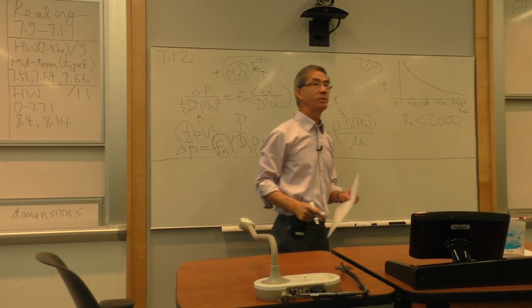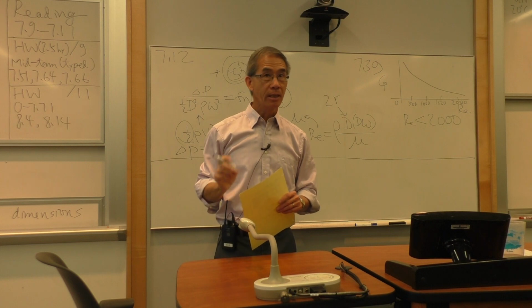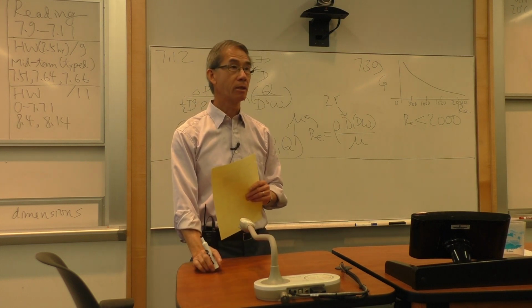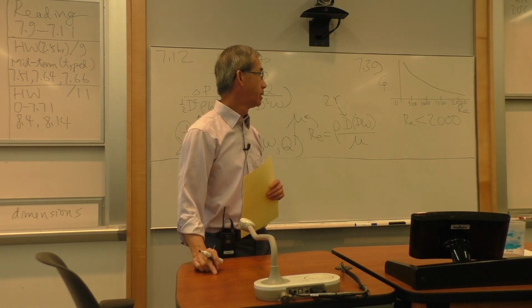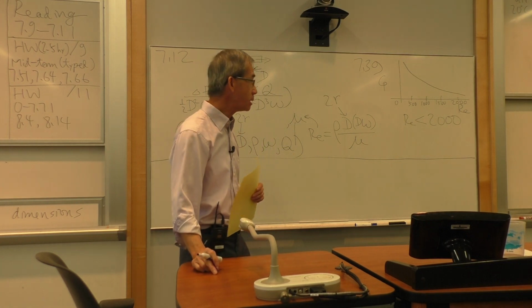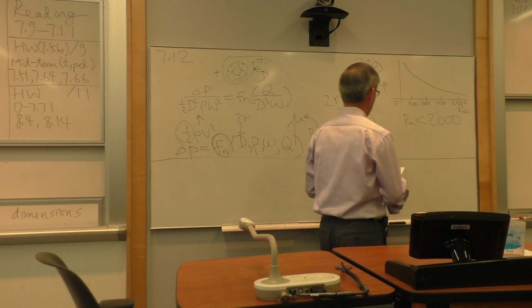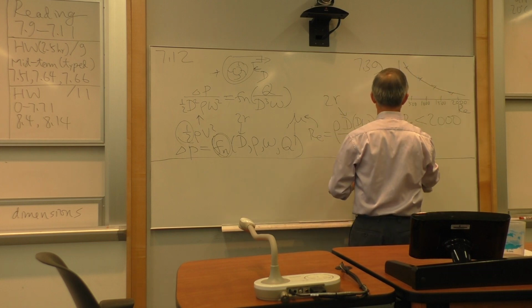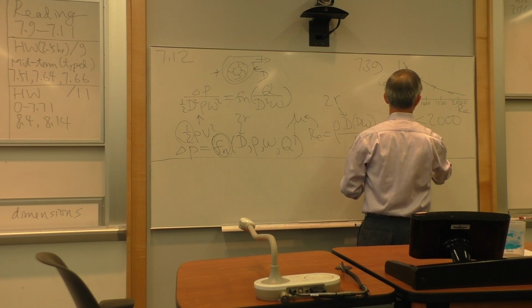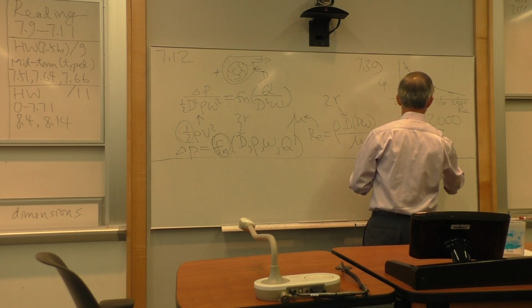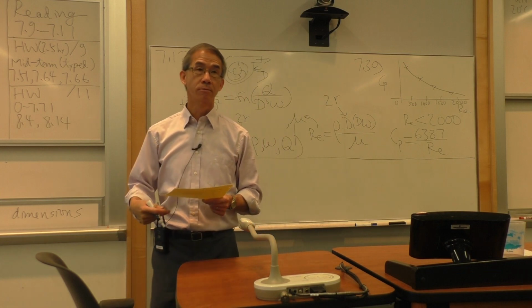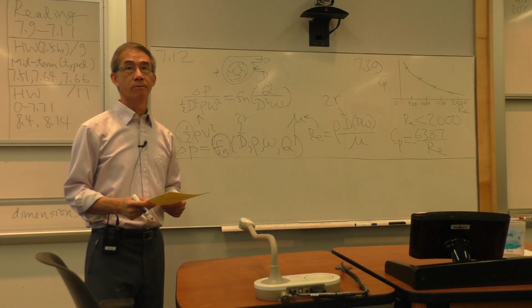What type of flow do you expect in the pipe? Laminar, and we'll touch on what that means. It's laminar, meaning that if you curve fit these 4 points, the relationship will show you is the reciprocal or the log of 1 over Reynolds number.